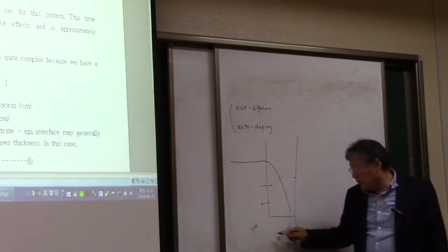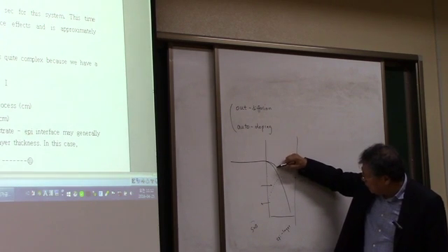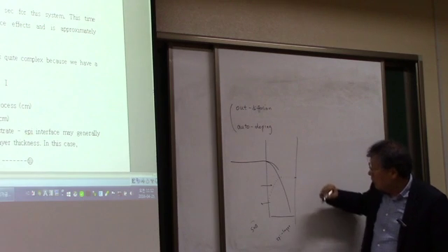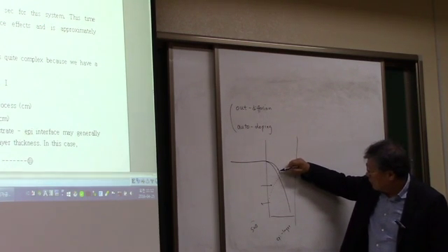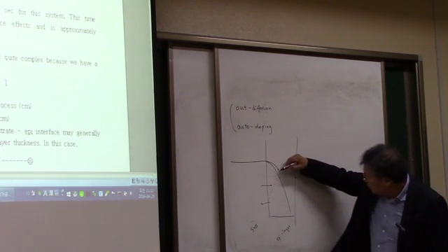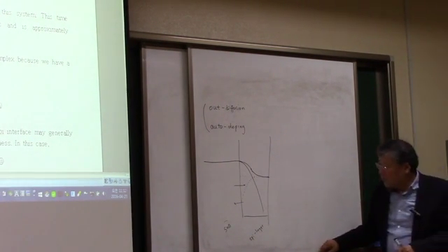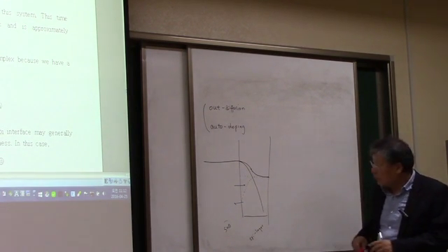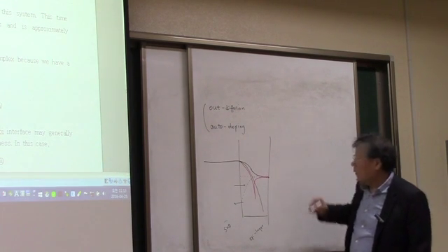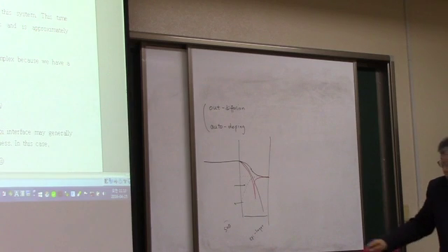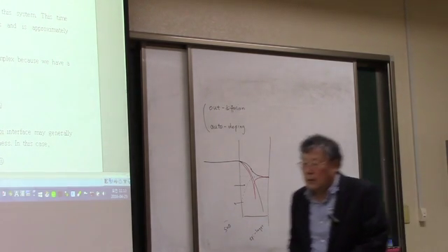Now, if we have the same type of dopants, these two things are going to be added to end up with some part, let's see, some part that is something like this, okay? These two dopants are going to be added. Now, if it is the opposite type of dopants, then you're going to have this dopant profile, right? If the dopant in the epitaxial layer has an opposite type to that in the substrate.